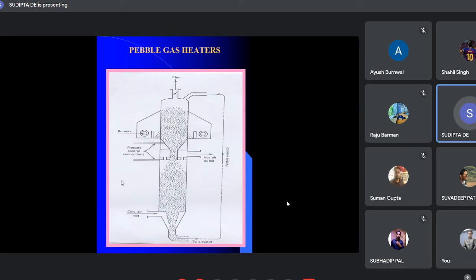Third, we have run around coil, we have discussed there. Simply a liquid is flowing through these different temperature gases and transfers heat from one section to another through the finned heat tubes. Run around coil is not a very efficient system for substantial heat transfer, but it is a very cheap option to get some gain.